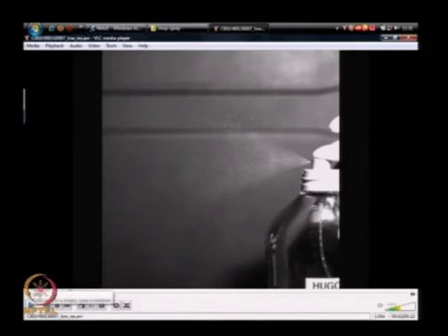Now, if I take another frame just a short instant later, I can look at those same white specks that have moved a distance downstream. So, by knowing the distance that these specks have travelled and the time spacing between the two frames that I just used to illustrate this point, I can extract a velocity vector.